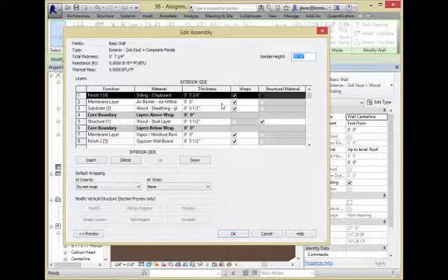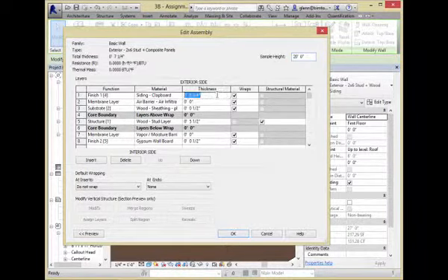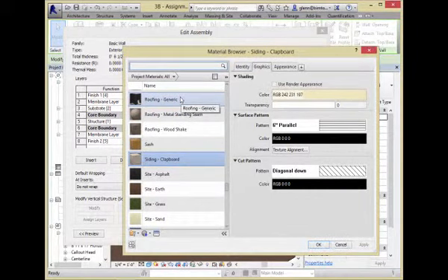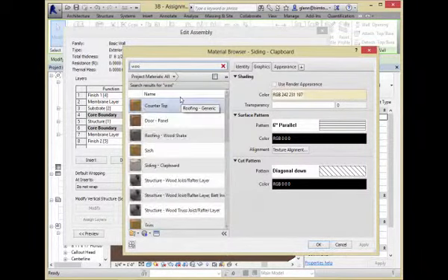Every material has a thickness. You can decide how thick your panels are. Maybe these panels are 2 inches thick. On top of that, we can change the material. I have it set to siding clapboard right now. Let's take a look at the materials you have to choose from. Over here in the materials column, we can type in materials, but I often click this little dot, dot, dot button, which takes me to a browser. It shows me all sorts of materials, and we can take a look at what's available. There are a lot of materials in there. Do some woods.